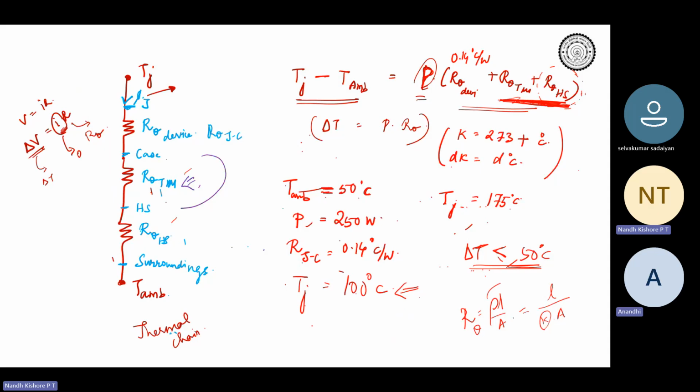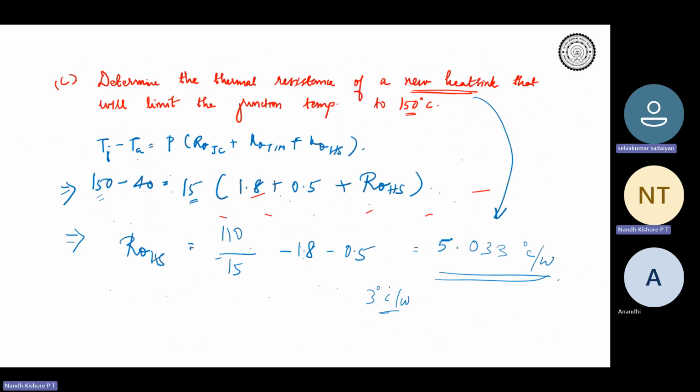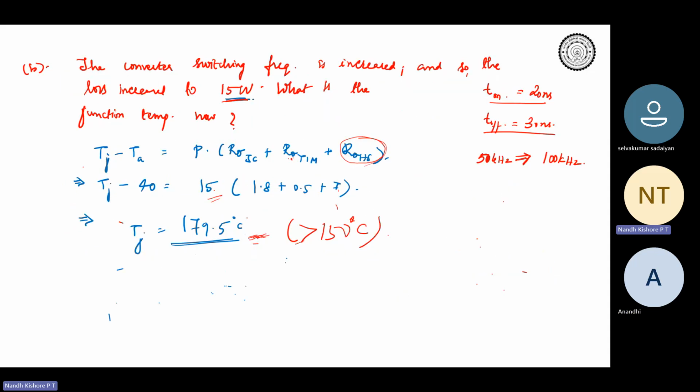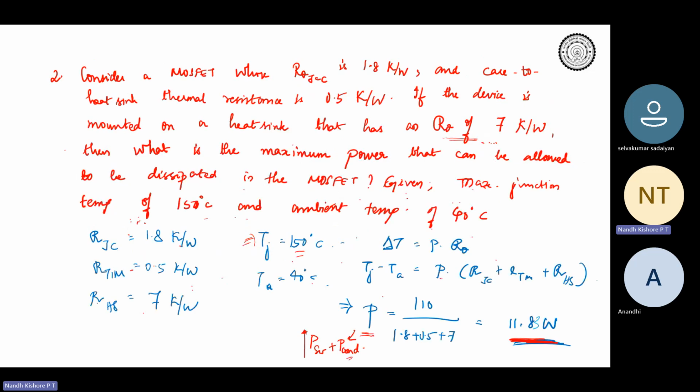Okay, and then here one doubt, sir. Actually, the delta, the junction temperature, because of 179 is that we are finding the R theta, no? From 179 we have to bring it down to 150. So then the TJ should be 179, no? No, no, no. See, we found out that the point is with the same heat sink, right?